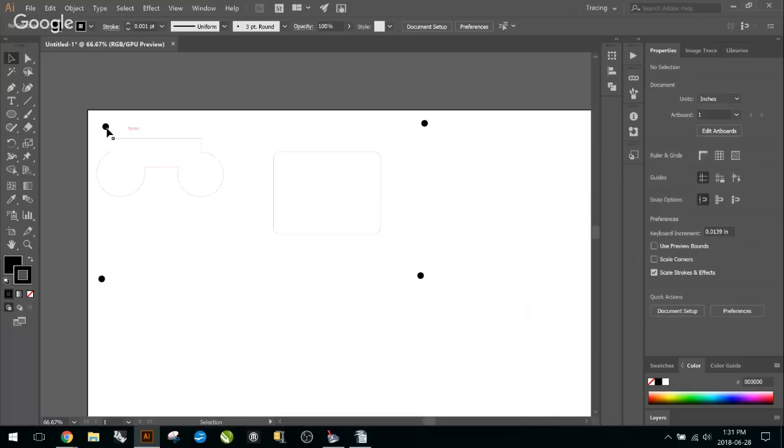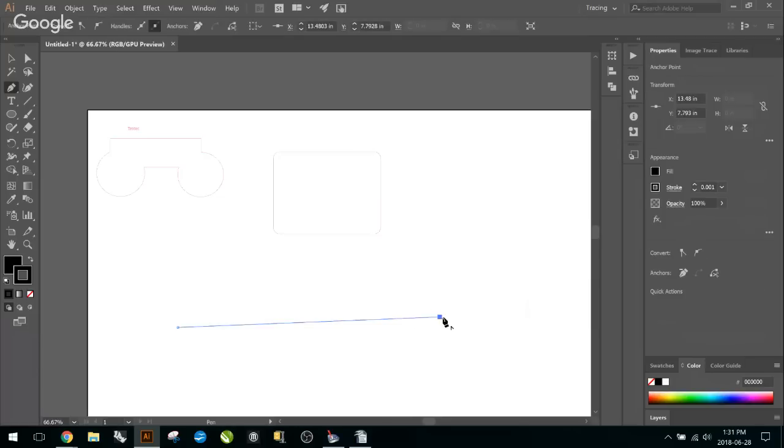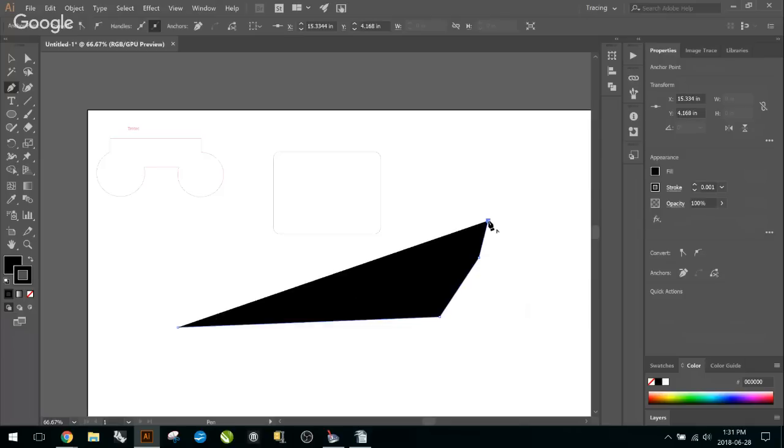Okay, we'll move on here. So next, we'll show you a great tool, the pen tool. Come over to your tool options here, click on your pen tool, and if you click on any 2 points on your material, you'll start to create a line. So these lines, obviously, you can make cut lines, or if you continue to click, you'll continue your line.